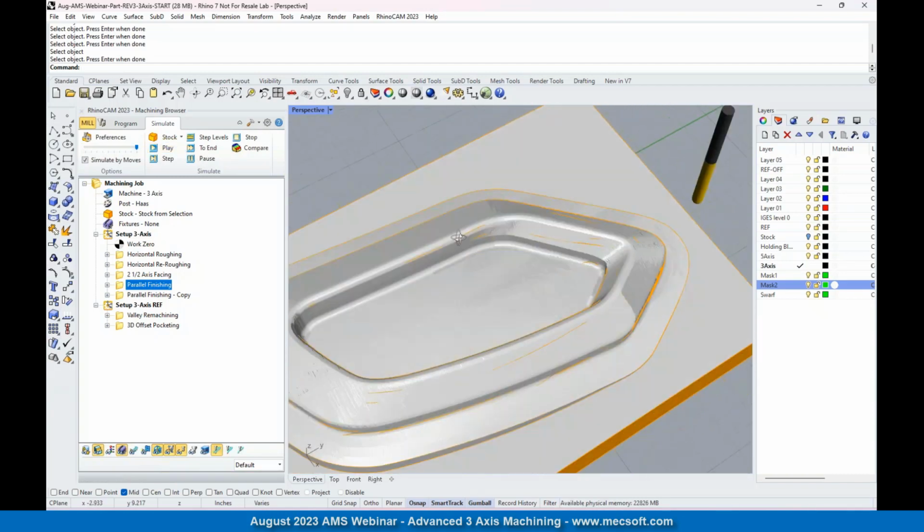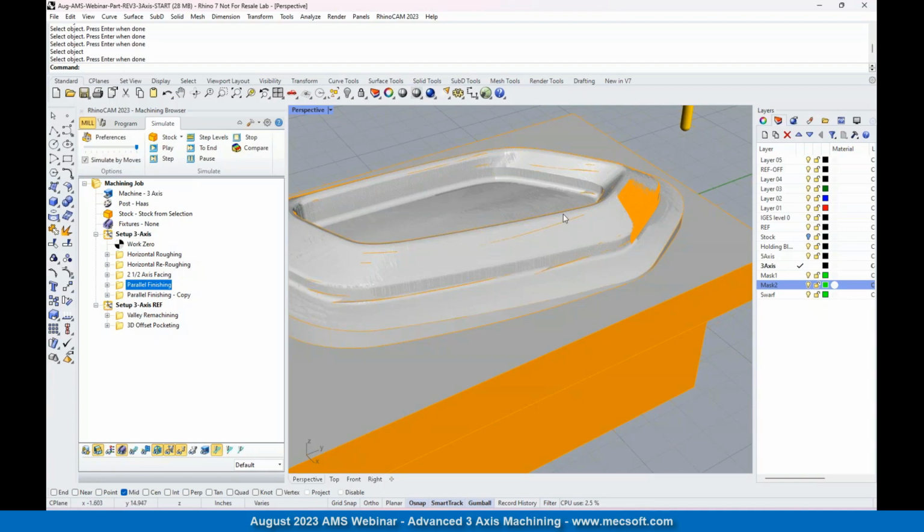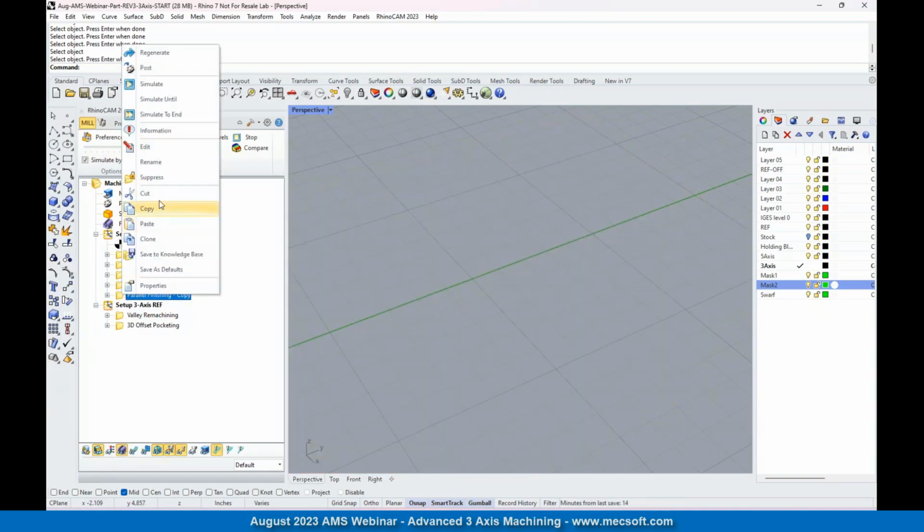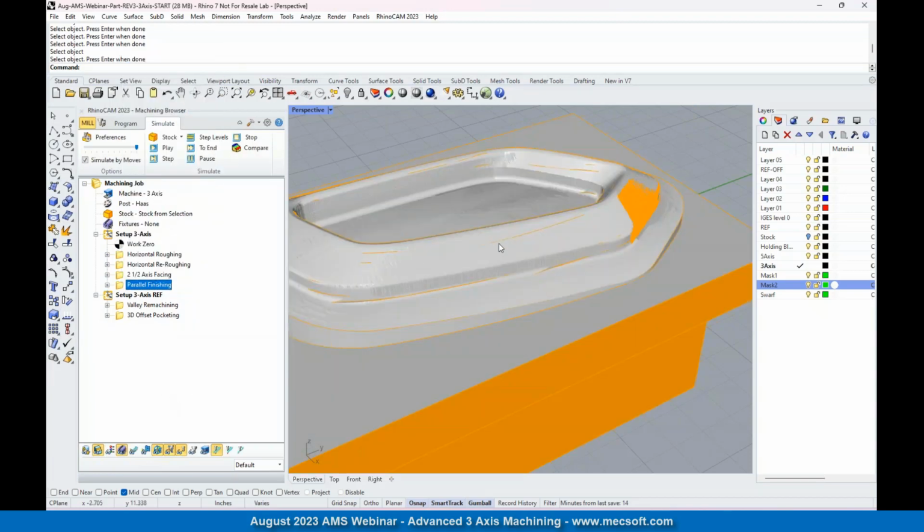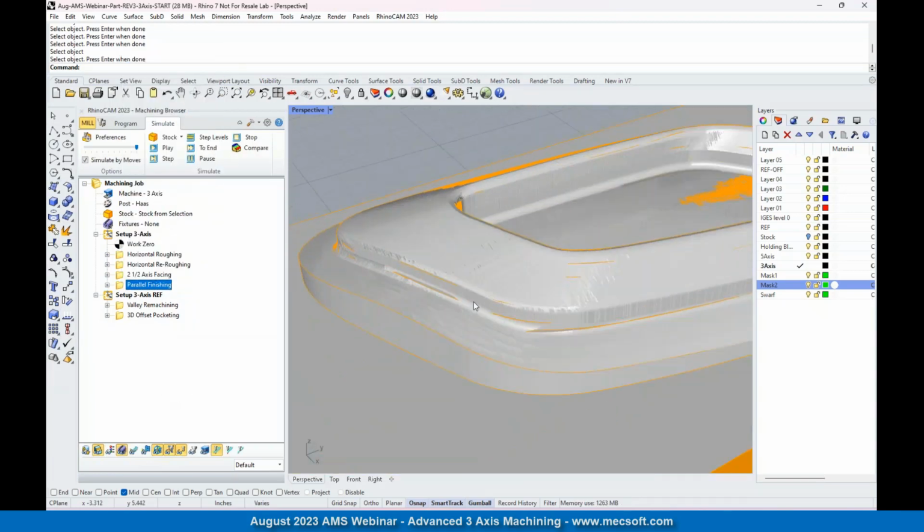Okay, so there it is in one direction. That is probably sufficient. I don't think we'll even need this one. So I'm going to cut this out. Because this, again, is pre-finishing. It looks pretty good, so I'm going to continue on. So the next, I think you used a very tight step over on that as well. So yeah. Okay, so next thing we're going to do is a professional toolpath called curve machining.